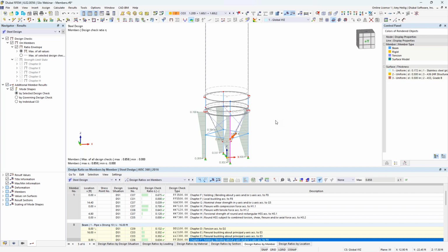So when we are performing a general static analysis, buckling is not necessarily considered. Now, if you're running a second order or a large deformation analysis, the program will give you an instability if you exceed the critical buckling load of either a surface or a member. But it's just a general instability without much more information. So how can we take structures such as this to evaluate buckling considerations? Well, if you remember, I activated the structure stability add-on.